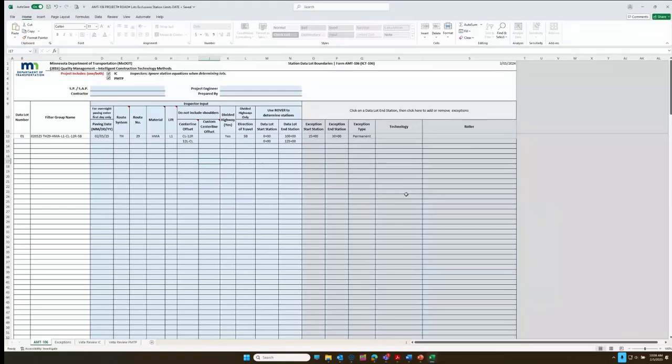And then the second is some control points, right? That's pretty common when you're using the GPS technology for anything else. So, and generally I look for on IC minimum of 5. If it's a real short job, you would need at least 5. And then if it's a long corridor, 1 every 2 miles or so is generally good enough on alternating sides of the road.